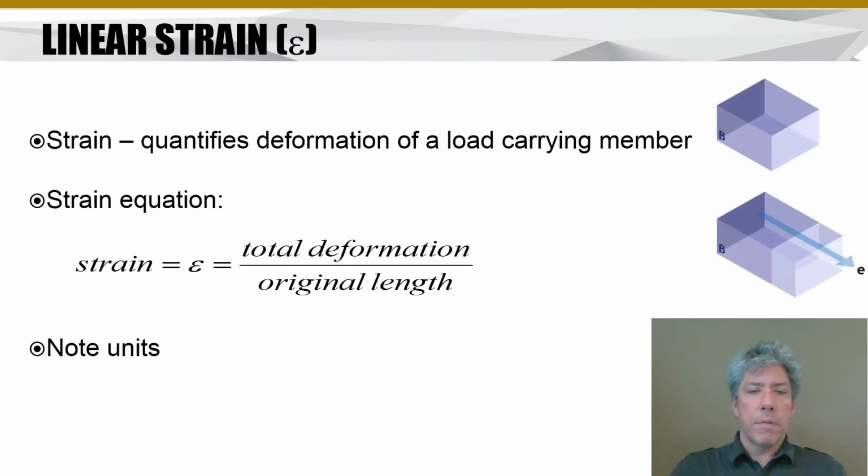Now, our topic for this lecture is strain. And let's start off with linear strain. So strain is just a way that we quantify deformation of a member that's under load. If you think about strain, you probably prefer to think about stretching. If you think about a rubber band, I'll use this example quite a bit, if you take a rubber band and you pull it, you're straining it or you're stretching it.